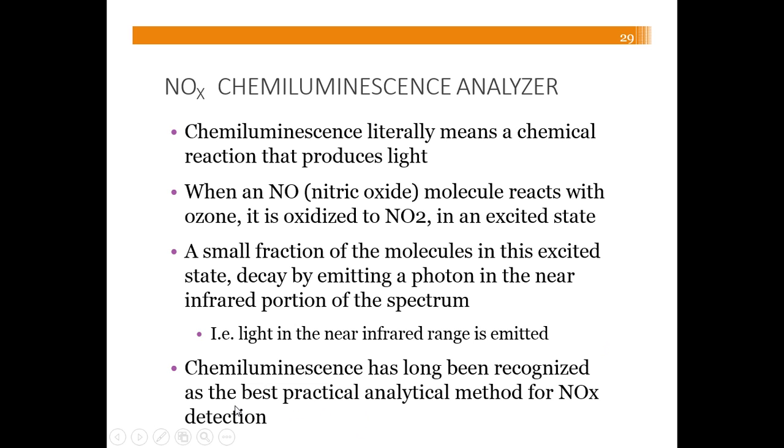Chemiluminescence has long been recognized as the best practical analytical method for nitrogen oxide detection, or nitric oxide detection. The amount of light that is produced is in proportion to the amount of nitric oxide, the particular gas pollutant, in the sample of air.